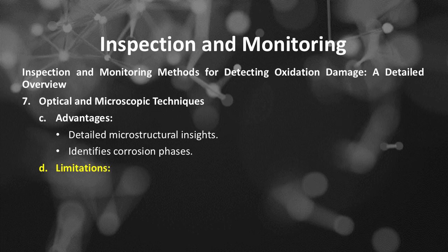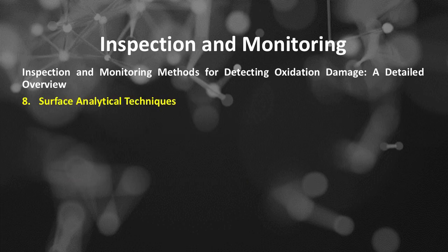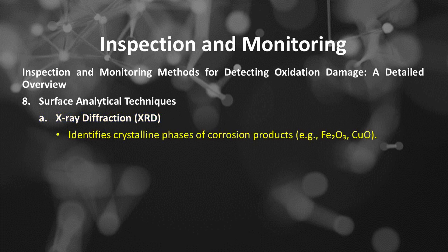Optical and microscopic techniques limitations include: expensive, requires sample preparation. Inspection and monitoring methods for detecting oxidation damage. Number 8 is surface analytical techniques. Number A of surface analytical techniques is X-ray diffraction or XRD. Identifies crystalline phases of corrosion products such as Fe2O3, CuO.